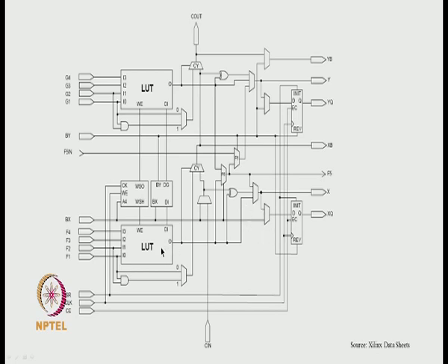Okay, now you should know that there is a slight issue with it. When you have a lot of separate lookup tables combined, suppose you want a 16 by 16 memory, that means 16 locations of 16 bits, then you have to parallel 16 of the lookup tables to get a 16 bit width of the memory.